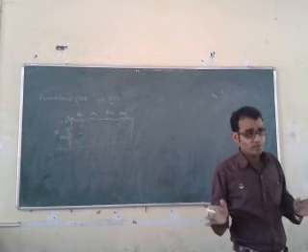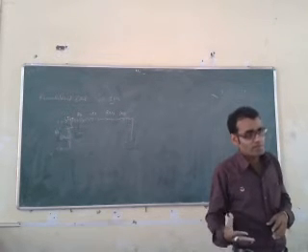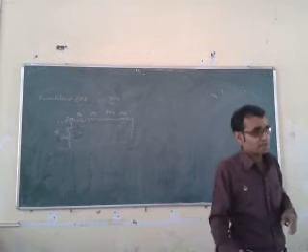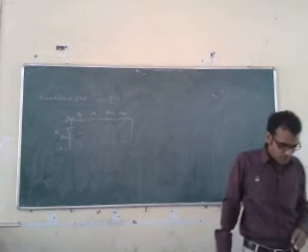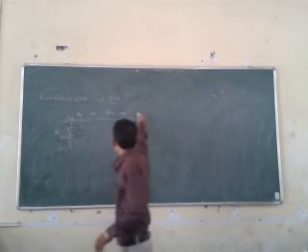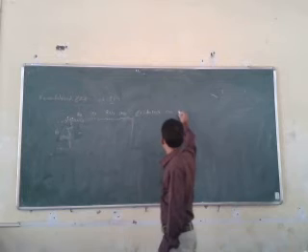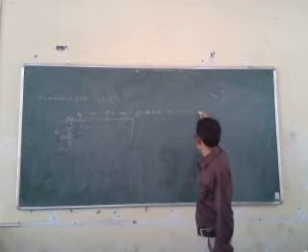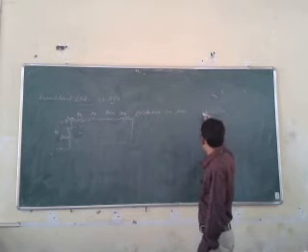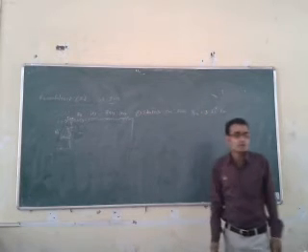You should write down some of the equations important for this topic as well as for the examples, and finally for the future exams, and then for the internal and the external exams. So these equations you should remember, starting from the first, stator copper loss. Stator copper loss is 3 times Is square into R. We are saying PCU, so copper loss.